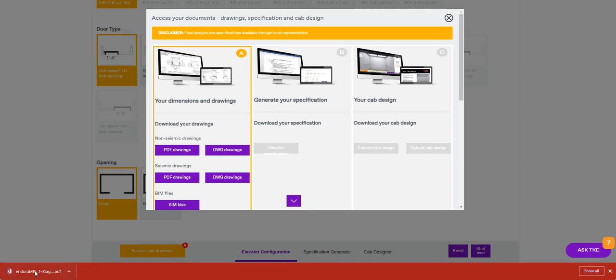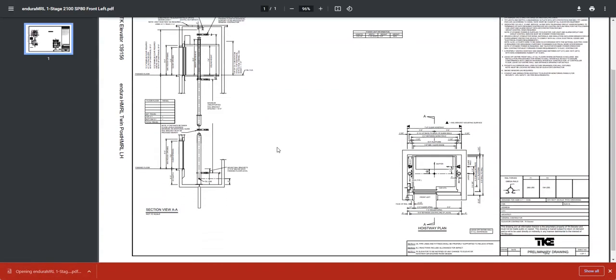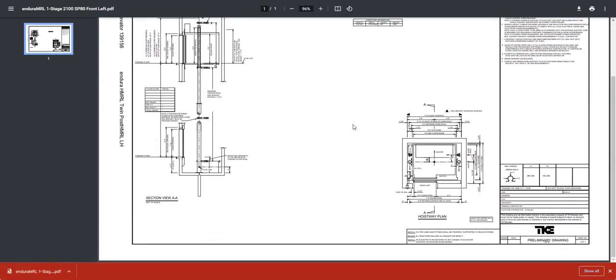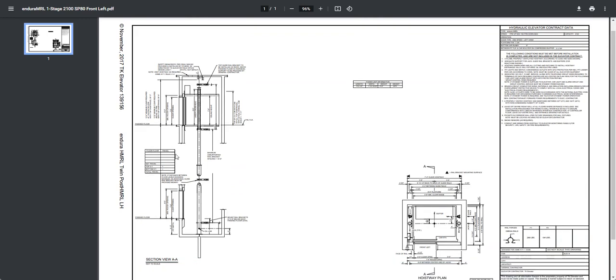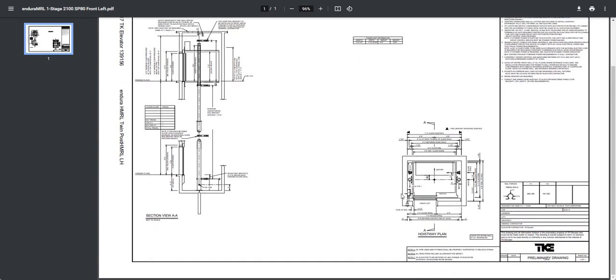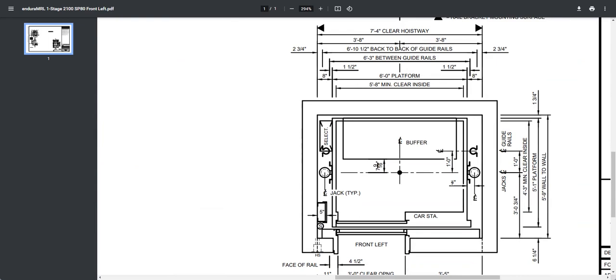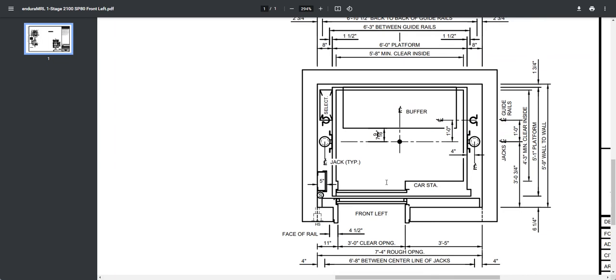And then it will open this up, and when you open that, it'll tell you basically this is like the section that the elevator requires, and this is the elevator size inside and the hoistway. Okay, so if we look at this one carefully, it says that the clear hoistway, I'm sorry, 7'4", is required for this kind of elevator, and you don't need a machine room.